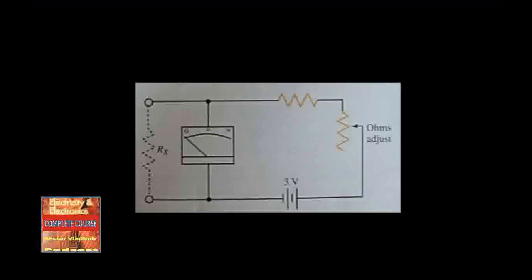A shunt ohm meter is connected as shown in figure 2-14. In this circuit, the unknown resistance, or Rx, is shunted, or connected in parallel, across the meter. Low values of Rx cause lower currents through the meter. High values of Rx cause high meter currents. When the ohm meter is connected in the shunt position, the indicating needle deflects from left to right in the manner of the ammeter and voltmeter. Zero resistance is on the left. The scale increases from left to right. Figure 2-14, schematic diagram of a shunt ohm meter. Note that the meter reads in the opposite direction of other ohm meters.